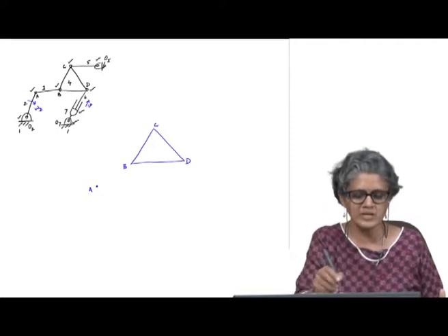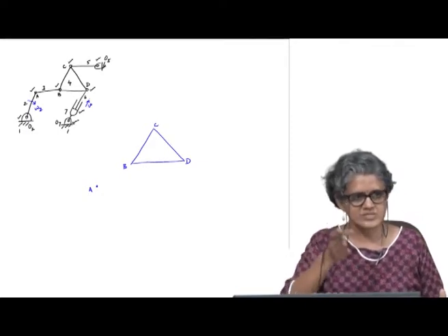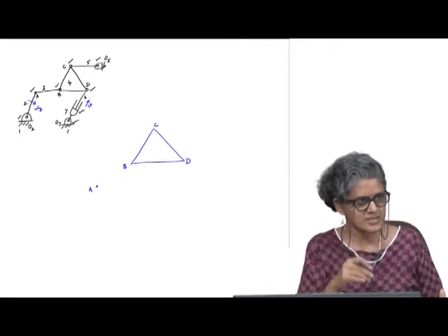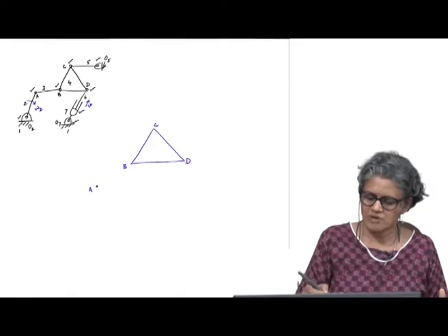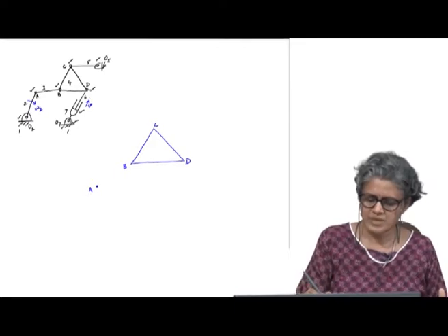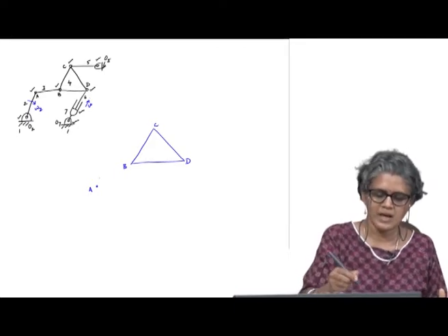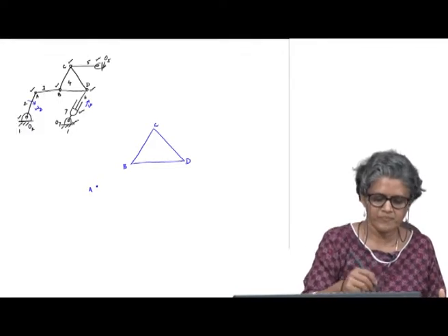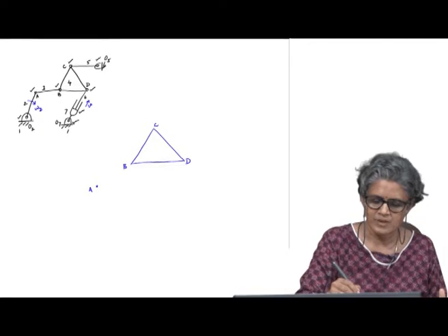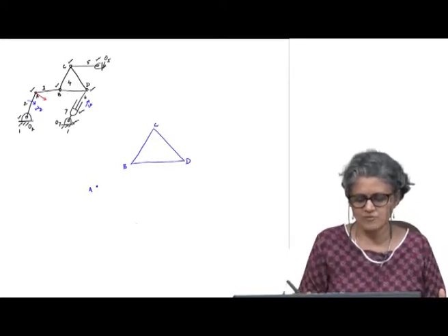I have omega 2 and I am given the velocity at which this hydraulic cylinder is expanding. Okay. So, if I look at A, I know the velocity of A completely, right. So, this would be the velocity of A.